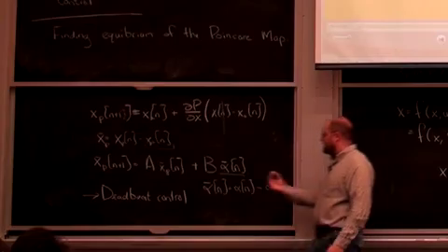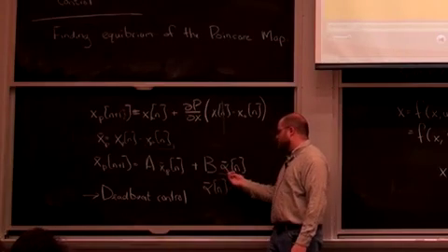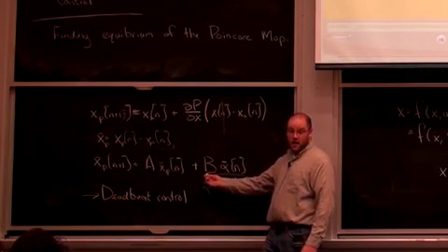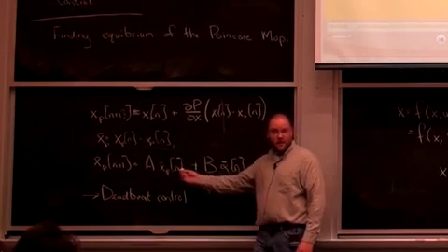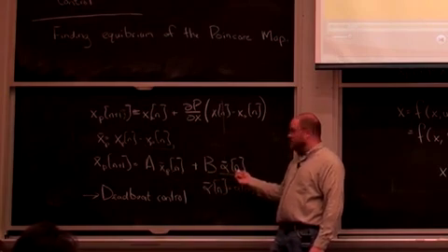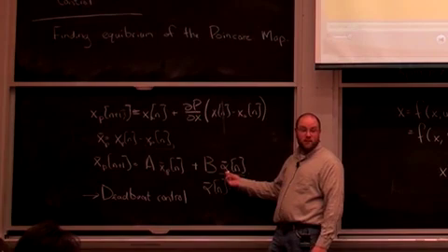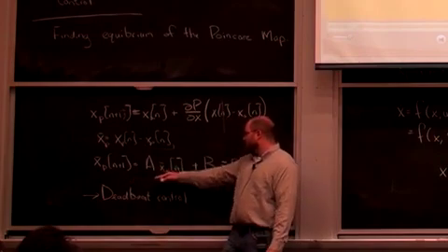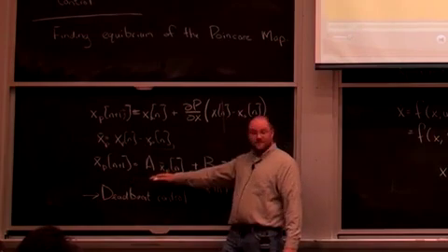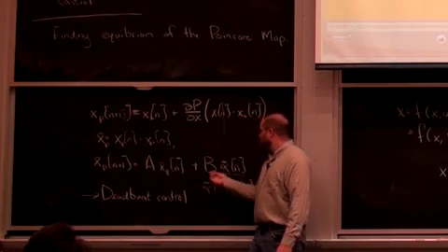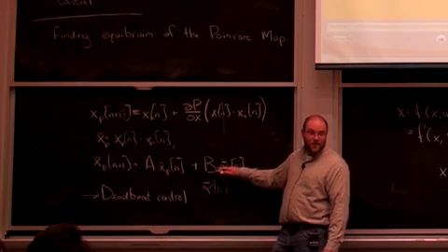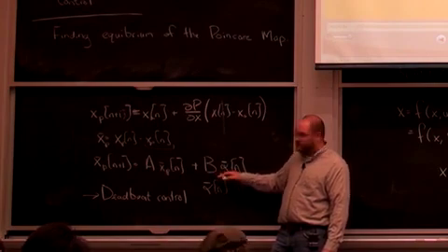Certainly you can do that here if you have no limits on alpha, and if B is full row rank, then it's just an algebraic equation to compute what alpha n had better be. It's like feedback linearization. I could just cancel that out. Sometimes you can't do it, but I want you to know that it's a beautiful goal for control.